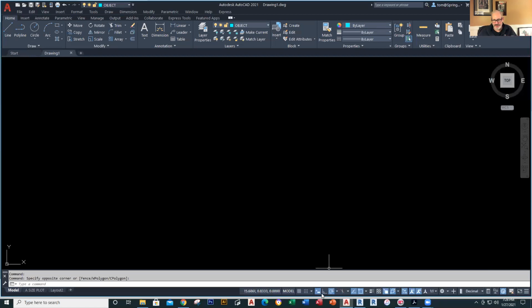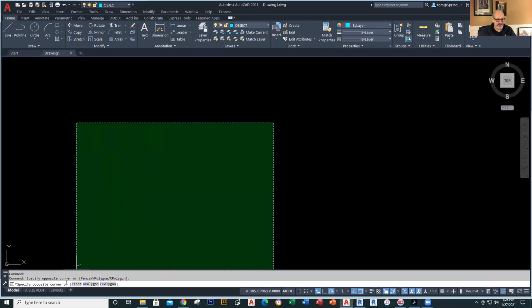What I do is these four icons right here, I'm going to hover my cursor. On this one, you see a picture of a plus sign in a little prompt window. Look at my cursor, that's the plus sign. Now watch what happens when I click and start to pull it along. I've put mine in a purple highlight. That's called your prompts, also called your dynamic input. It's a little bit of information that follows your cursor around the screen, and it matches the same information that's down here on the command line.